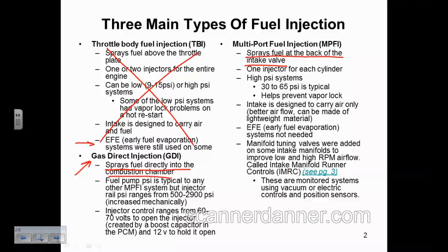From what I've also read, these injectors are switched on both sides, that both control wires go to the computer and they actually switch both sides of the injector, both the power and the ground. That's what I've read. I can't confirm that, but there may be some differences with testing. But there are also similarities. We've talked about power and ground side switching and how to handle that, and I don't think it's really going to be that big of a deal to transfer that information into working on another on-off solenoid, if you think about it.